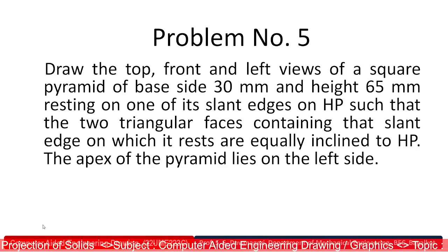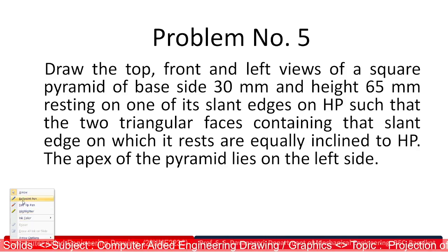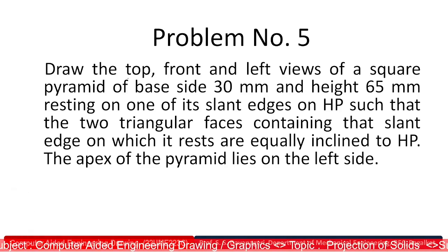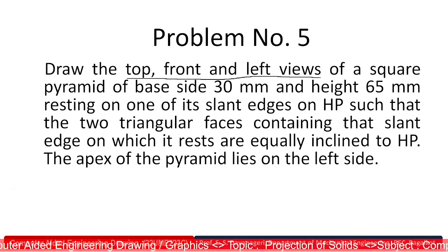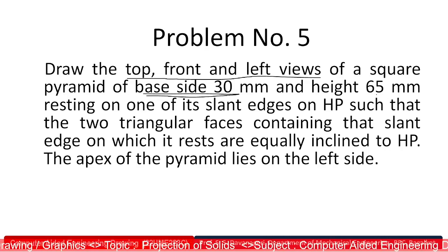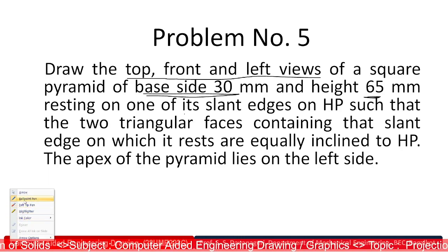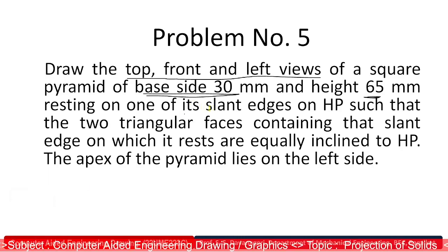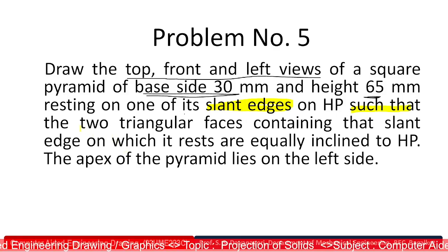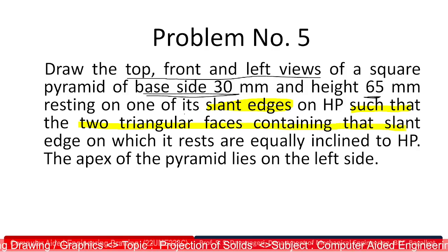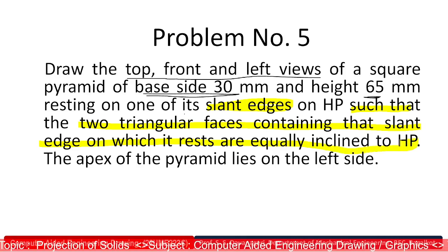So this is problem number 5. You need to draw the top, front and left views of a square pyramid of base side 30 mm and height 65 mm, resting on one of its slant edges on HP such that the two triangular faces containing that slant edge are equally inclined to HP.